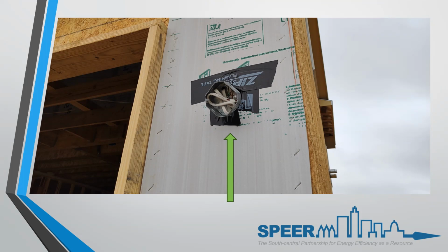This electrical box is on the front corner wall of the garage, so being airtight is not needed. Just the flashing tape meets the requirement of having a water intrusion barrier. And in most things with code, a specific product is not specified, a brand is not specified. It's not listed in the language anywhere.